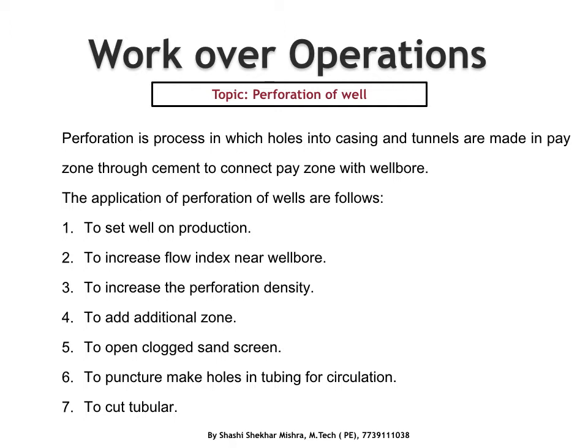Another application of this perforation is to increase the flow index near the wellbore. Suppose the well is flowing for a long time, and due to clay and other debris deposition near the wellbore, the perforation tunnels get clogged. So that can hamper the production and increase the skin. That can be overcome by re-perforating the same zone with the perforation gun.